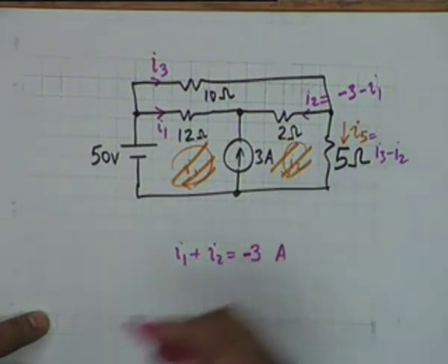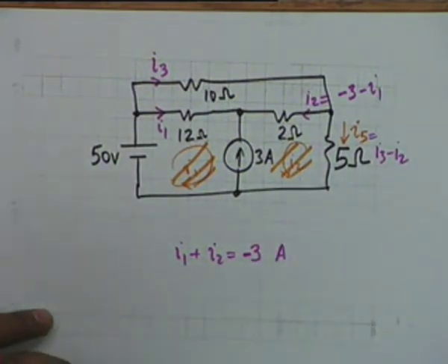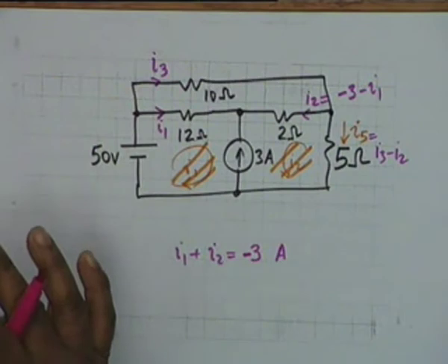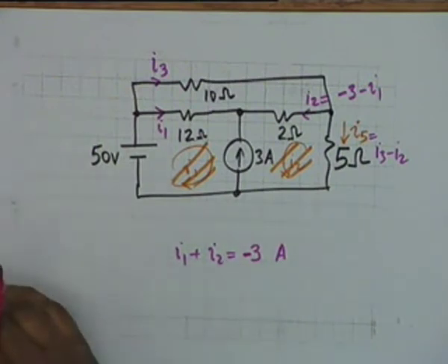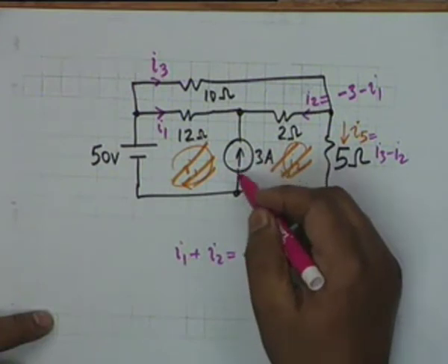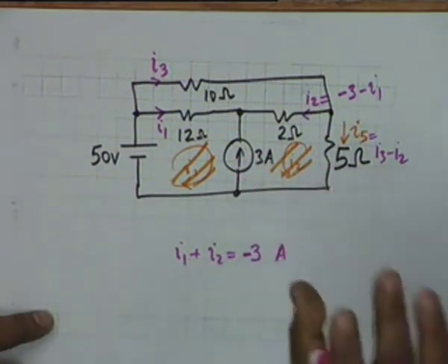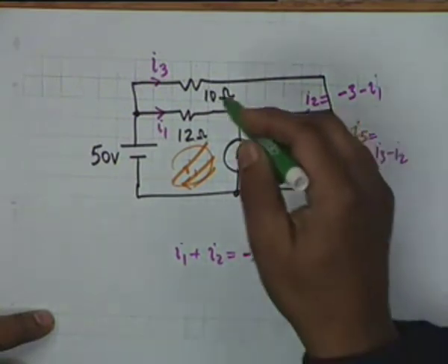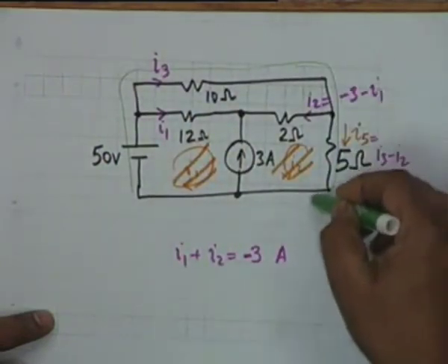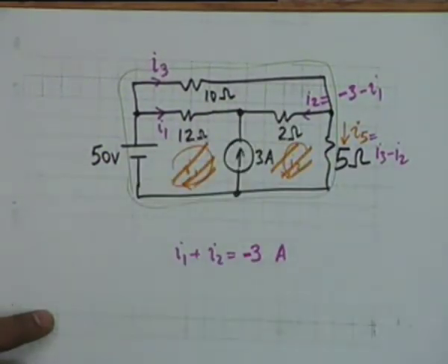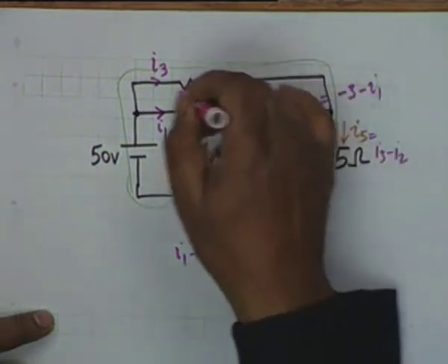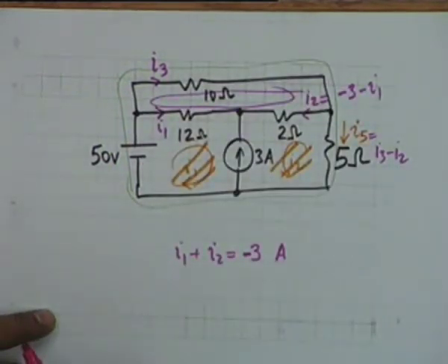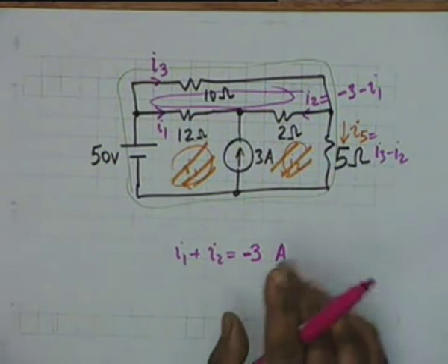Alright. And therefore how many currents are unknown? Only 2. And it suffices to write 2 loop equations. Now, carefully avoiding the current generator. The current generator must not be inside a loop. So what is the choice? The bigger loop. Well, you can go like this. This is one loop, and the other one is the upper loop. Okay, 2 loops which do not contain a current generator. That is enough, because there are only 2 unknown currents.